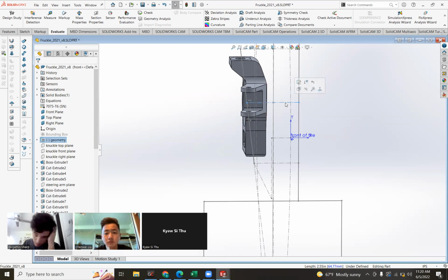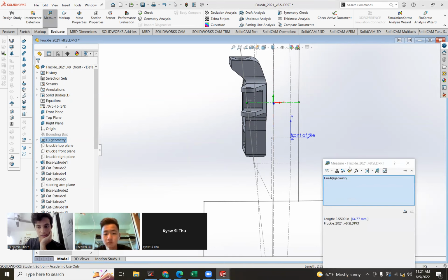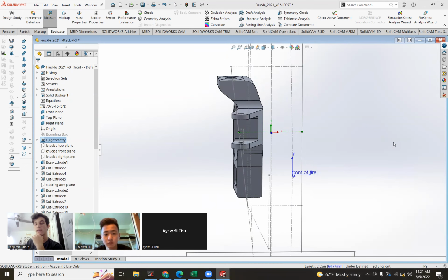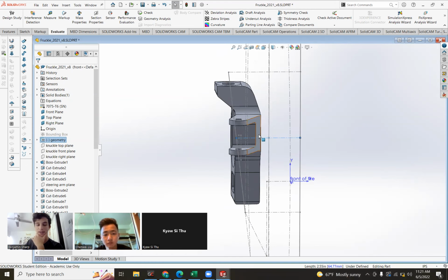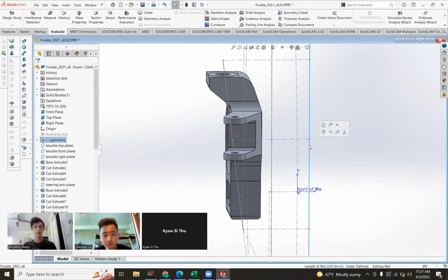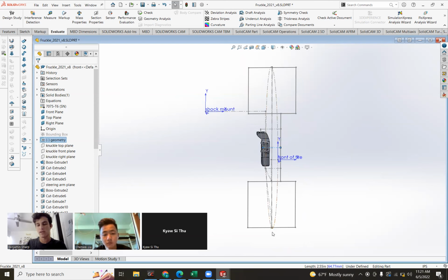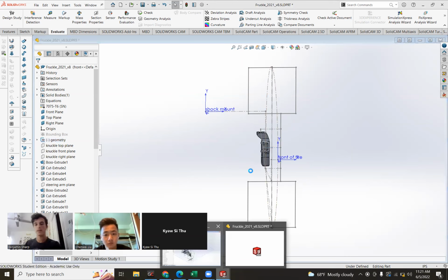Before, it was incorrectly modeled as the length of this member right here. And I might have even kept it that way because it's just way easier, but technically it's supposed to be to the center of the tire, not to where the rim is. Because if you remember, the rim of our tire, the face that we bolt to, is not in the center of the tire. It's offset. But spindle length as a number doesn't matter that much. The only thing that does matter is the effect of spindle length on scrub radius, which is a geometry thing, and I'll go explain that right now.